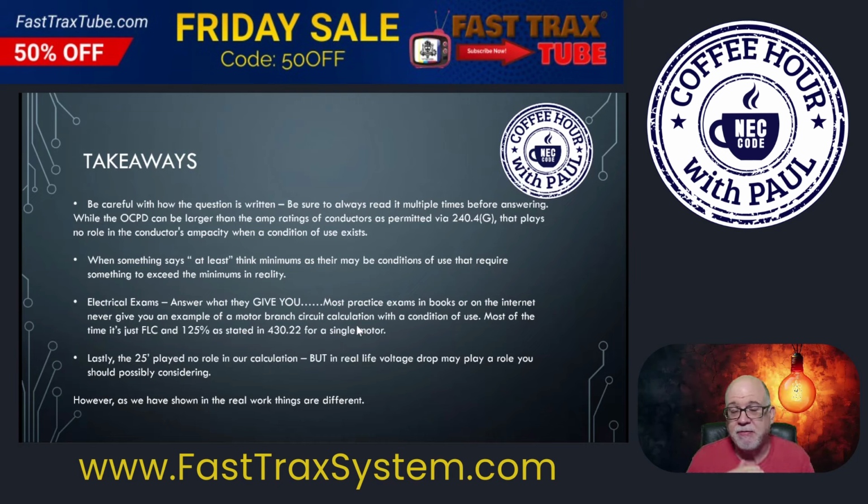And typically, even for these applications in the NEC, voltage drop is a recommendation, it's not a requirement, okay? Except for sensitive electronic equipment and fire pumps. Other than that, it's just good electrical design. On an exam, they should not mandate you to do voltage drop because it's not a mandate in the NEC, unless it's those conditions I just said: fire pumps and sensitive electronic equipment, all right?